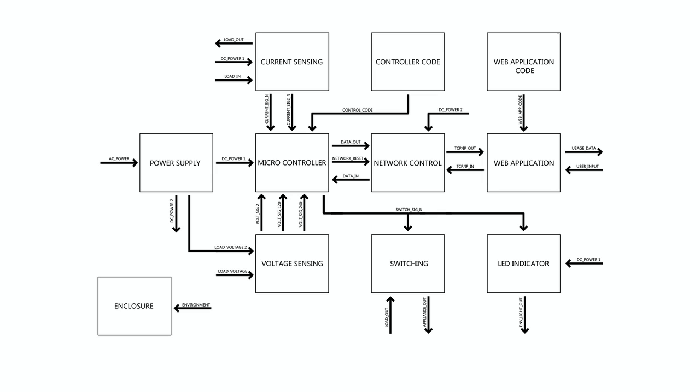Looking at the top level block diagram, you can see that the microcontroller is at the heart of the device. It takes incoming data from the voltage and current sensing circuits to produce power values that contain both magnitude and phase. It also controls switching signals for the solid-state relays, which turn the breakers on and off. The LED indicators are driven from the same switching signal, and it provides red or green light to visibly show the status of a device.